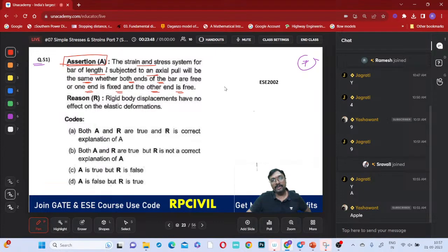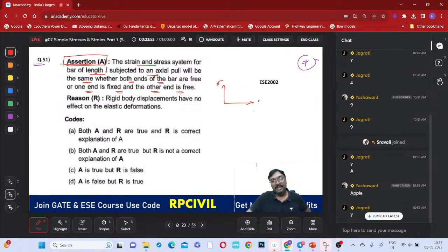Because the load deflection or stress strain curve is related to the dimensions and conditions, or is it related to the material? Is it a material property or a dimension or end conditions property? It is a material property, right? The stress strain curve is a material property. For the given material it will be the same, whatever condition it is in.